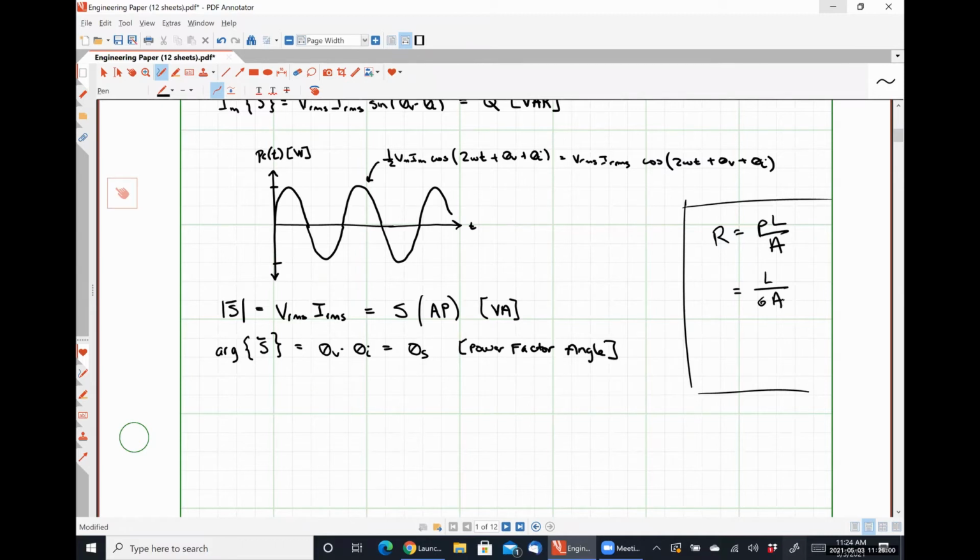So if you have a solid piece of wire, it's going to have a significantly smaller cross-sectional area, which means it's going to save you space. But the largest issue is its ductility and weakness. Whereas if you use a braided wire or a stranded wire, you're breaking up the amount of current flowing through each individual strand, making it much, much smaller, but it occupies significantly more space. But it's considerably more flexible.